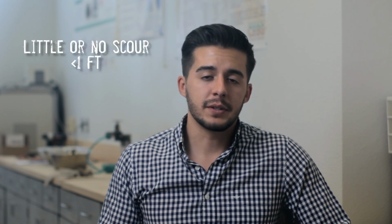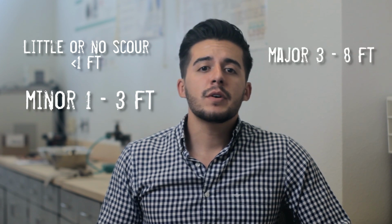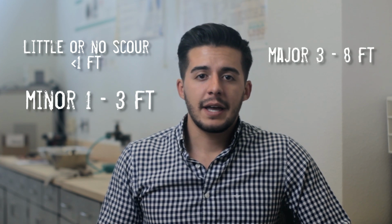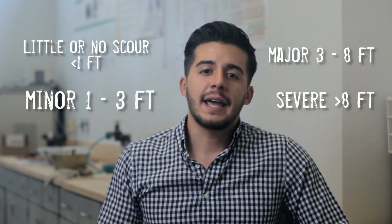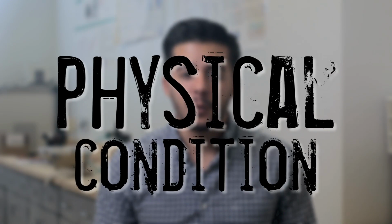Depending on the depth of the scour, we can classify it as little or no scour if it's less than 1 foot, minor scour for depths between 1 and 3 feet, major scour for depths between 3 to 8 feet, and severe scour if there's more than 8 feet. Now we're almost finished with the characteristics that a culvert inspector needs to check, and the next ones are probably the most important. The physical condition of the culverts.